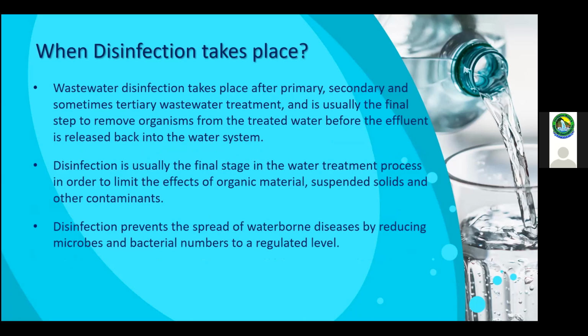So now that we know why we disinfect, and what exactly disinfection is, when exactly does disinfection take place? When is the best time to disinfect? Typically, for both water treatment and wastewater treatment, disinfection is the final step in the treatment process. For wastewater, it is usually after your primary and secondary treatment.